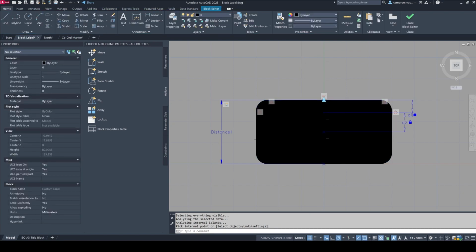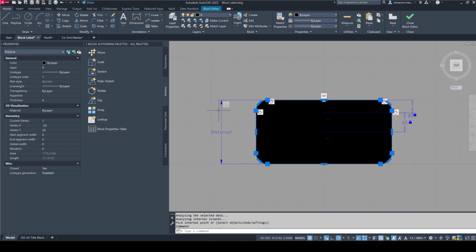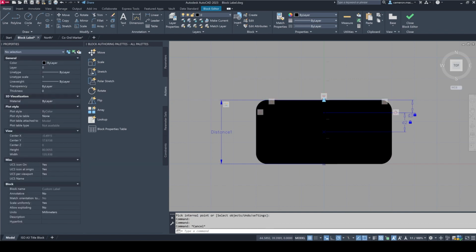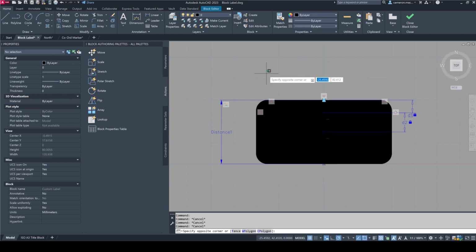And the last thing I want to do very quickly as well is the border of the component, the border of the block. I want to apply that same colorization rule as well, if it isn't already there. So in this case, it's not. The color is set to by layer at the moment, and I want this to be set to by block. So anything inside of your block that you want to have enabled to change color based on the block itself, we need to go and grab that by block option from inside there.